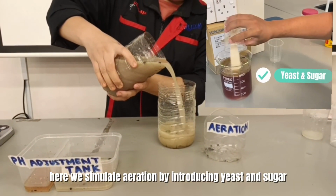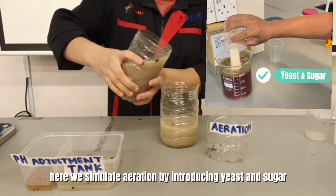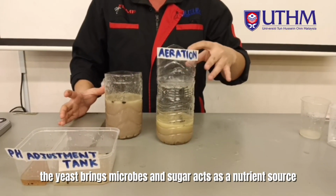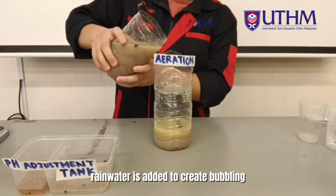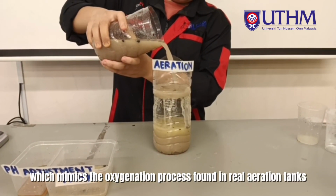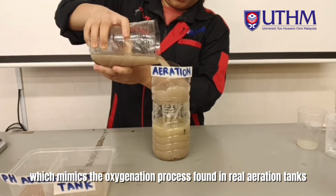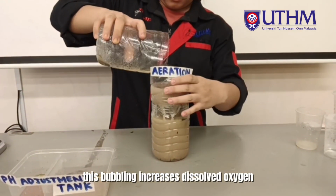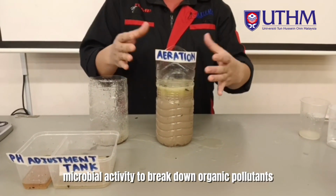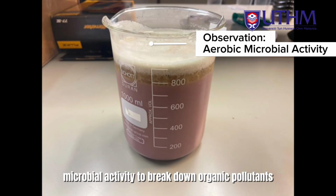Here, we simulate aeration by introducing yeast and sugar. The yeast brings microbes, and sugar acts as a nutrient source. Rainwater is added to create bubbling, which mimics the oxygenation process found in real aeration tanks. This bubbling increases dissolved oxygen, encouraging aerobic microbial activity to break down organic pollutants.